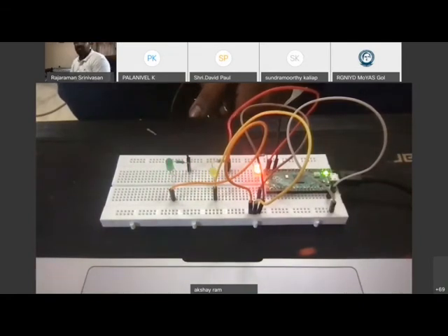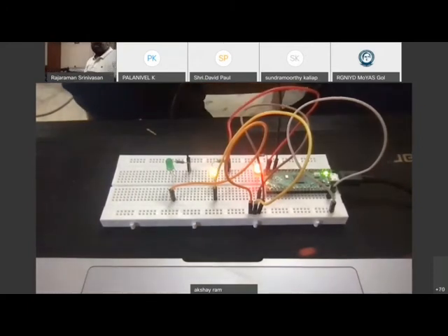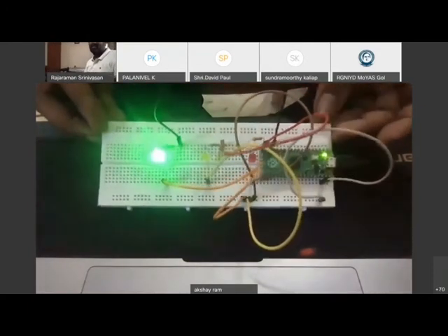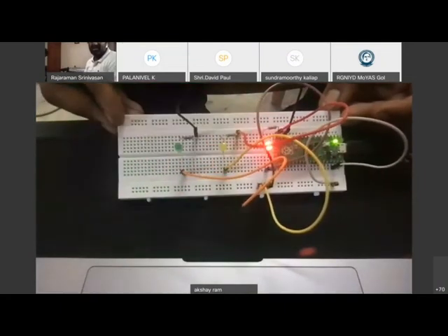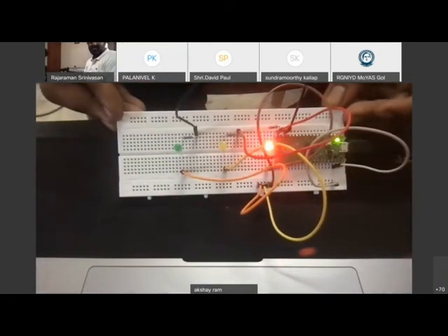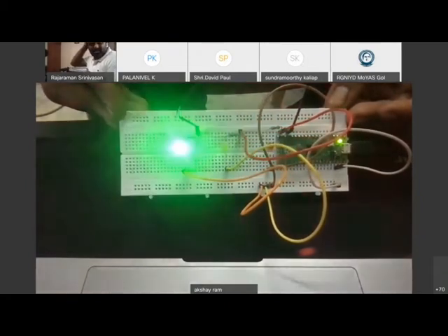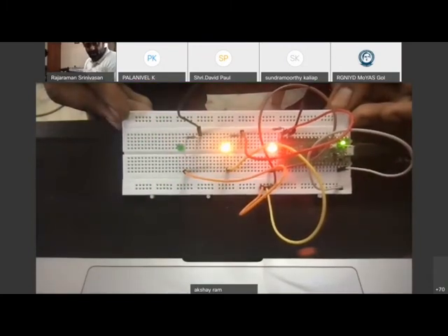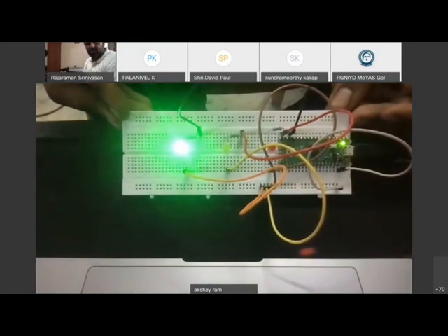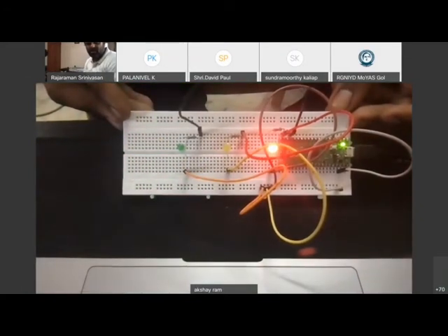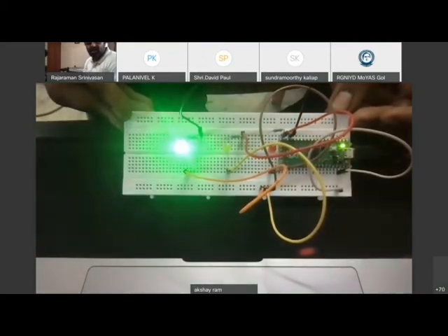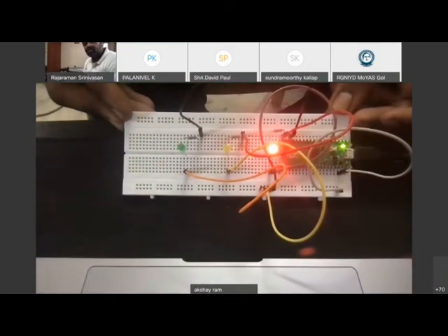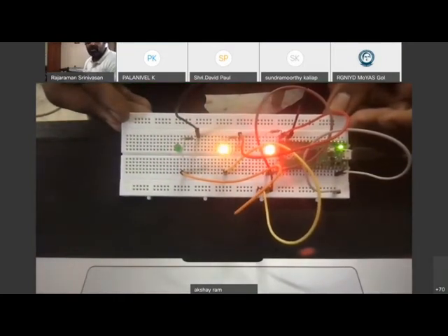On the screen, actually, look at it here. This is red now. Red itself looks like orange. Folks, if you are able to see, based on the program that we wrote, for 3 seconds red is on, and then amber comes along. For 2 seconds together, both the amber and the red are on, and then both of them get switched off. Then green turns on for like 3 seconds, then green switches off, immediately the red comes up. 3 seconds on red, and it goes into an infinite loop.